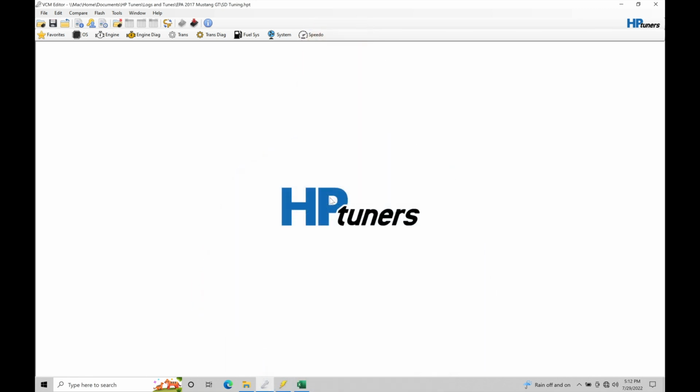Okay, so let's get started. We're going to be taking a look at dialing in our speed density on our Gen 2 Ford Coyote applications. Our speed density tuning is quite straightforward, but we need to make sure we have a lot of details covered in order to prep your VCM Scanner and your logging channels to allow you to dial in the speed density tables. I'm going to be walking through the entire process for one single MAP point, and then we'll talk about what we can do to dial in the other MAP points. We know we have a lot of MAP points with our VCT scheduling.